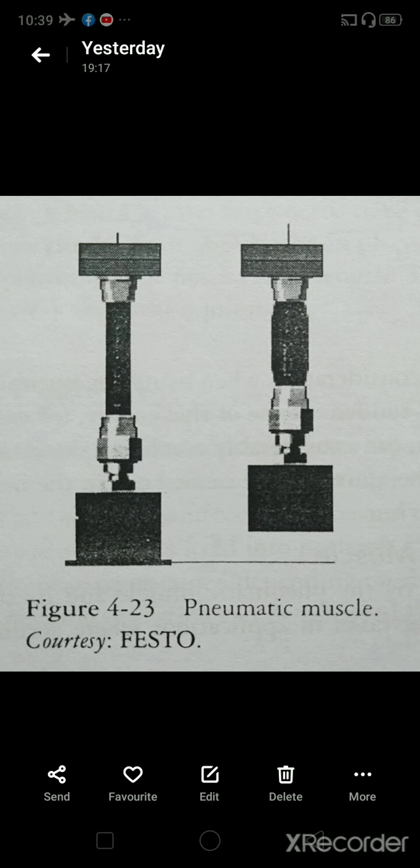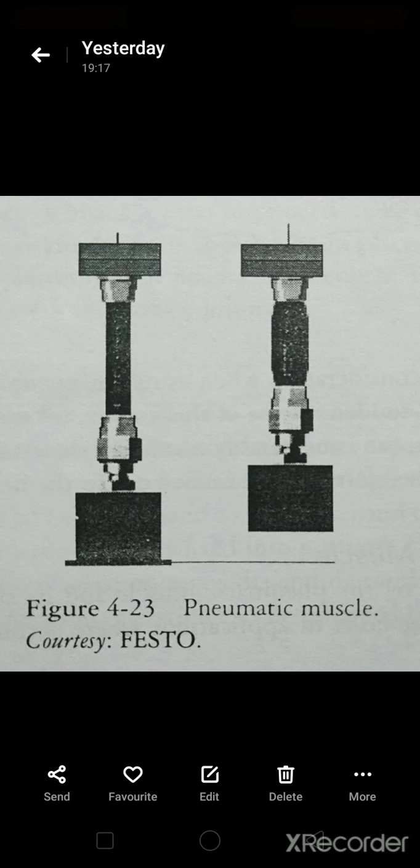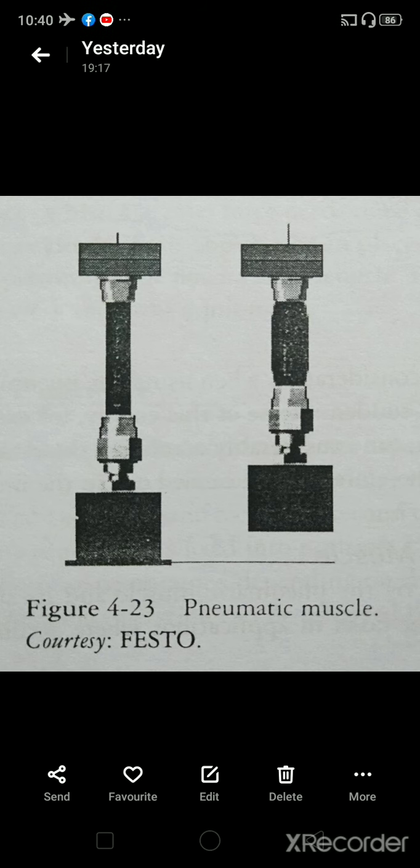Generally the maximum tensile force of pneumatic muscles depends on its internal diameter. It can be operated with compressed air or with incompressible fluids also. The materials used for the reinforced tubing are chloroprene and aramide, etc. Chloroprene is a plastic material of the elastomer group. Aramide is a reinforcing fiber made of aromatic polymers.